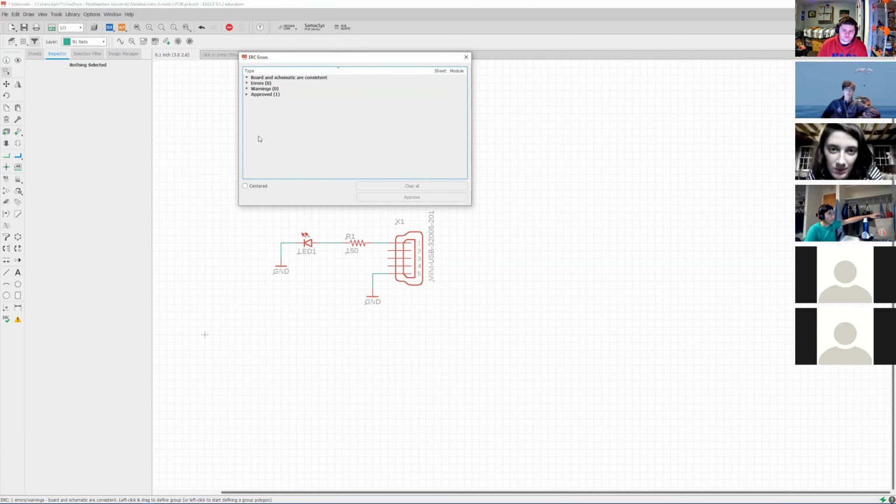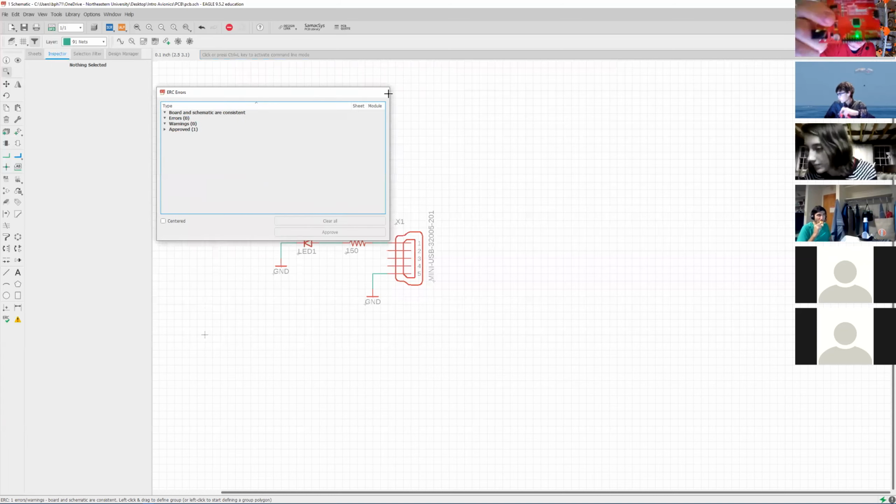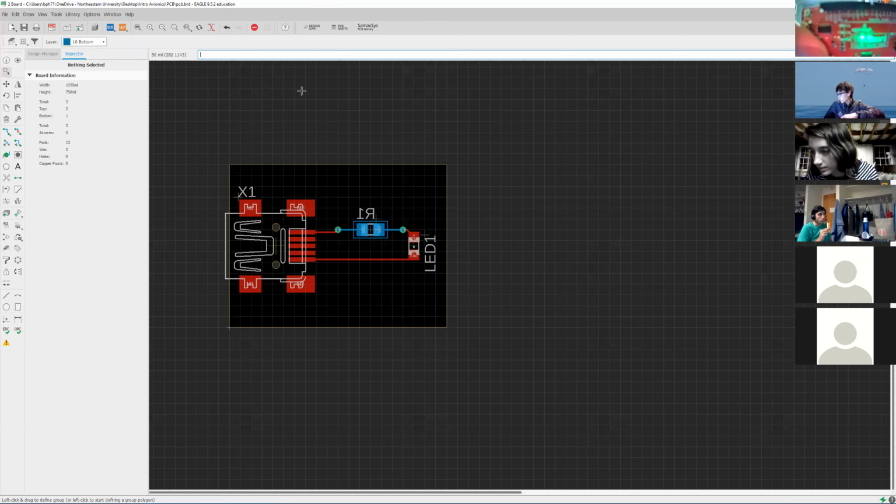So you could have something connected totally wrong, and Eagle's not going to tell you. Something you'll find later on. But in this case, there are no problems that are breaking Eagle's rules. So we'll just hit X, and then we'll go back to our board, and we will click down here, DRC. So DRC is the same as ERC, so electrical rules check, except for your board. It's the design rules check.